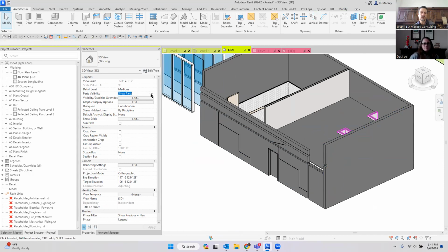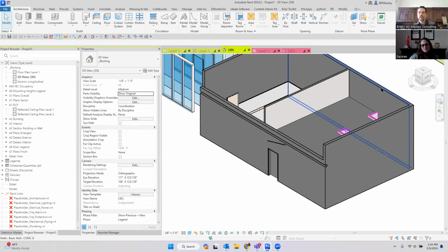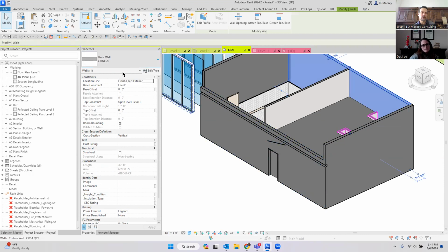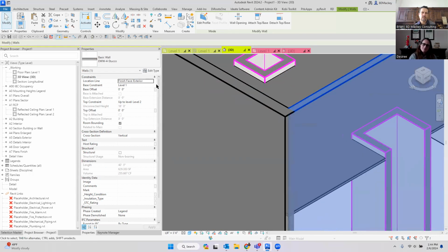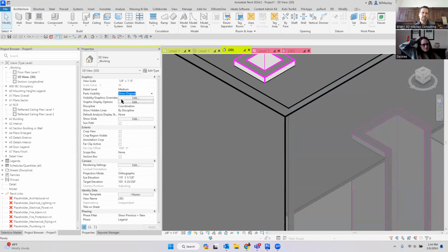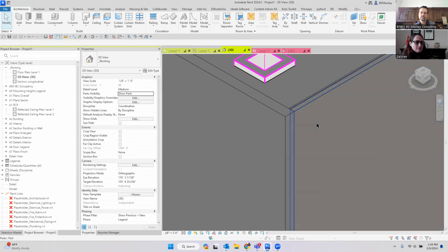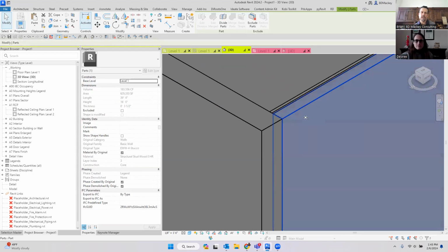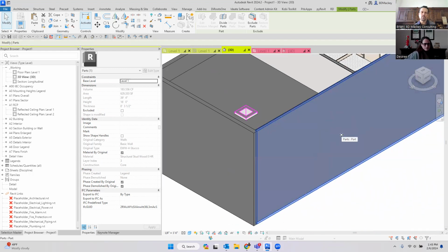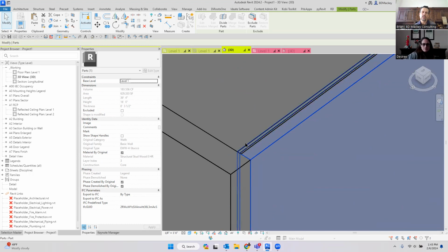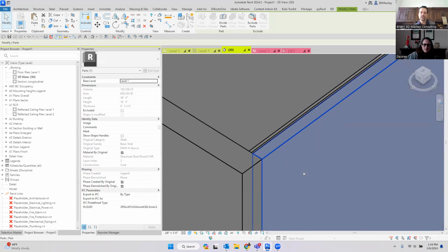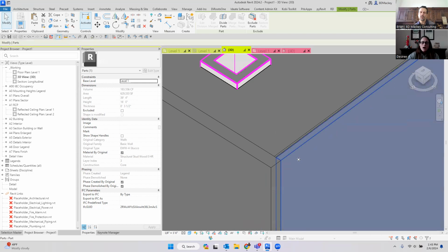and then we just started coming back, because if you part out a multi-layer wall, let's see, we're in show parts right here. Let me go back to original. Let me change this to be a multi-layer wall, not just concrete. Sure. And let's go back to the show parts. You'll see that this wall now, the EFIS became its own part. So I still have the gypsum board, the sheathing, whatever. We're going to pretend I think this wall's backwards. But you get the point here.